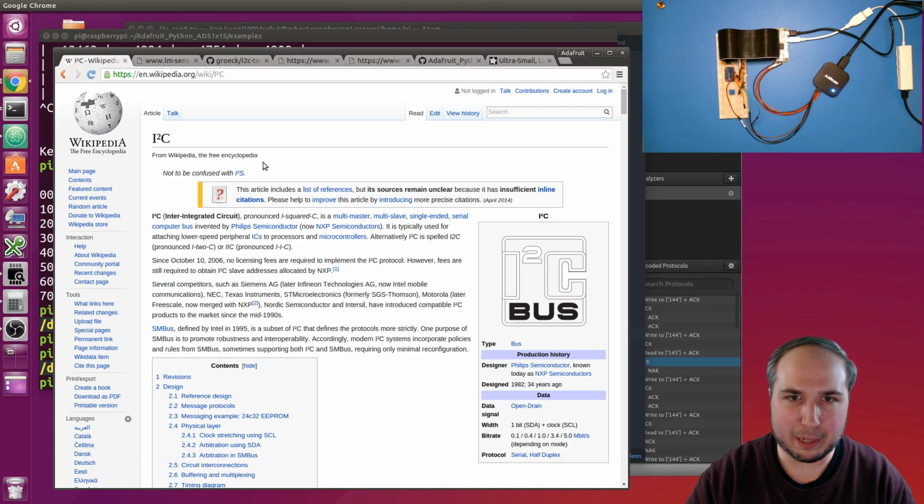It uses the same kind of protocol like we saw, there's a clock line, data line, but it's more register focused. So it's talking to devices that have a register that it wants to read a value from or write a value to. With I2C, you actually could just write a raw single byte if you want, but this smbus protocol is more to deal with devices that have registers. The difference really doesn't matter much.